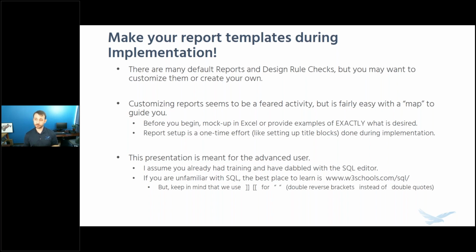Now there's one other thing to keep in mind: in the actual advanced interface for reports, we don't use double quotes. It says to use reverse brackets instead of double quotes, and that's just the way the programmers have written it to interface with SQL. If you're doing stuff in Management Studio, which is an interface directly into Microsoft SQL, you would use double quotes. Inside of SOLIDWORKS Electrical, you're going to use the double reverse brackets. Those replace the double quotes. You'll see that in some places that we'll be working on.